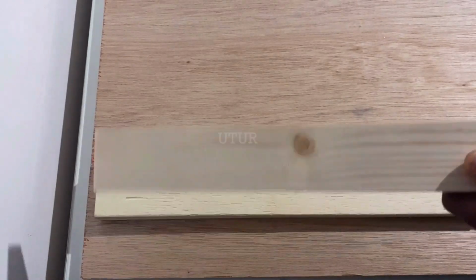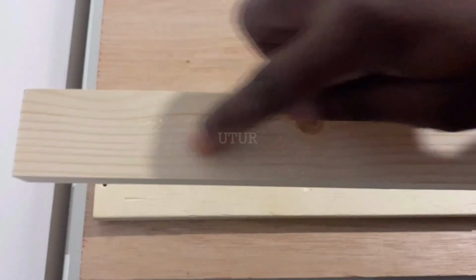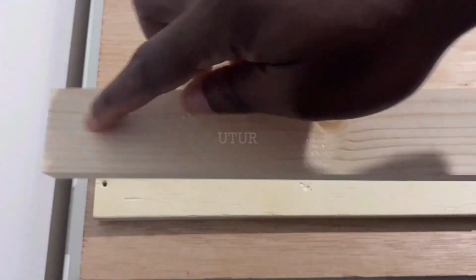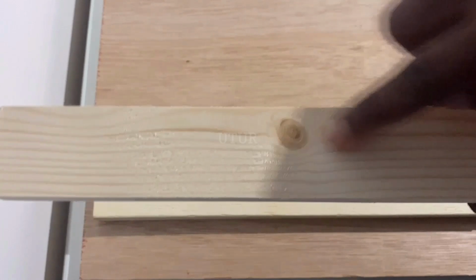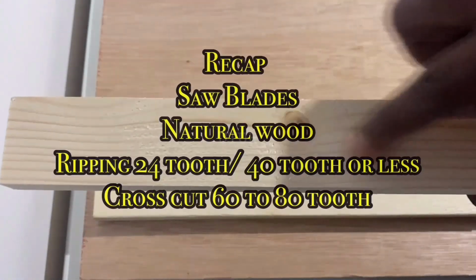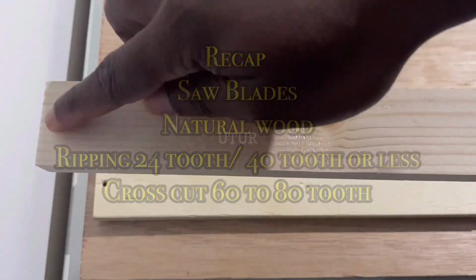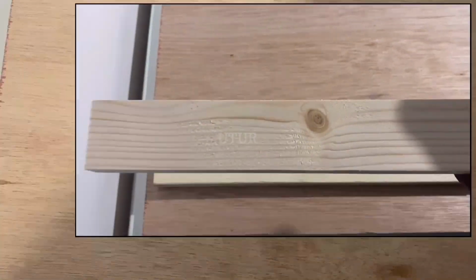Do not use a cross-cutting blade for ripping applications. And that's because if the gullet isn't big enough, it may not be able to excavate material from the gut, which leads to overheating. And so for ripping, you want to use 40 tooth or less, or typically 24 tooth. And for cross-cutting, 60 to 80 tooth.